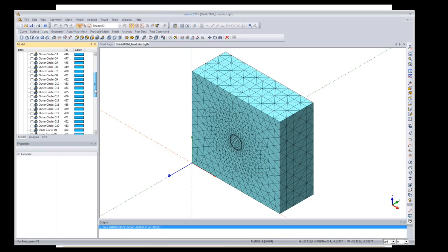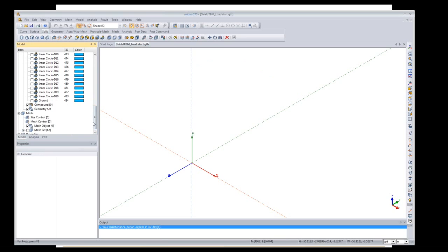So here I'll select the inner solids. Let me just undisplay all the mesh sets so they're not confusing. I'll click on inner solid, and since I'll be excavating in certain increments, I'll select 3rd, 5th, 7th, 9th, 11th.